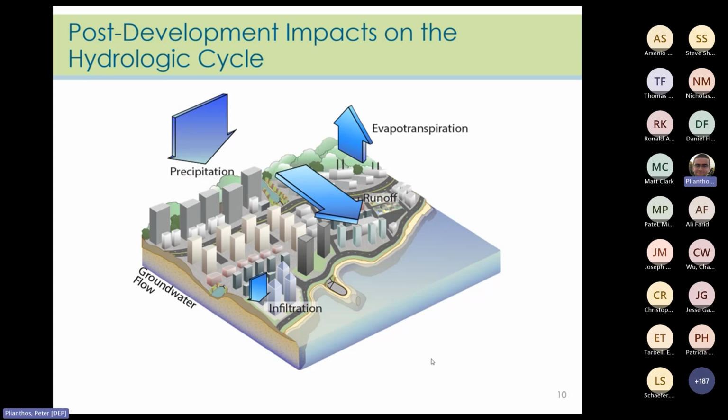This site also has a stormwater collection system that discharges to the water body. The insides of stormwater pipes are much smoother than vegetated surfaces, so the higher volume of collected runoff reaches the water body more quickly, potentially causing downstream flooding. Higher rates of runoff can also mean increased erosion and transport of sediment.